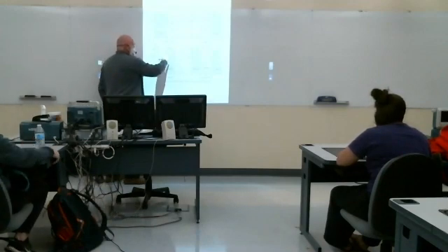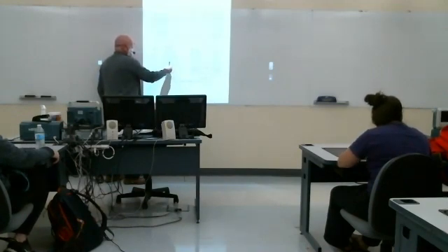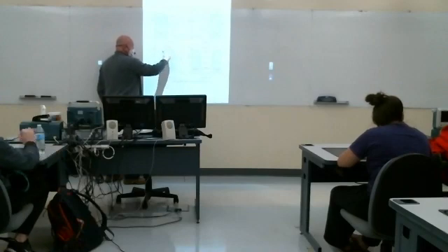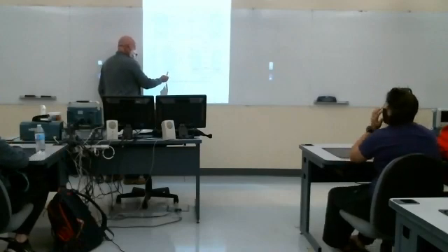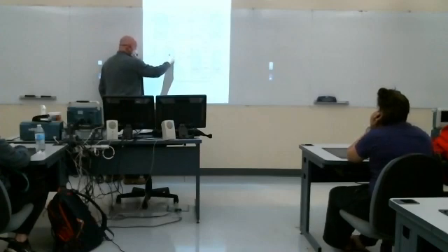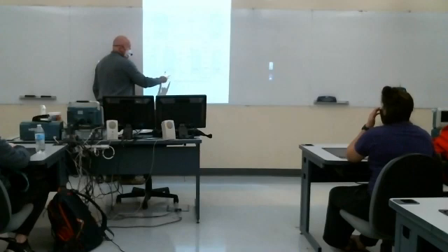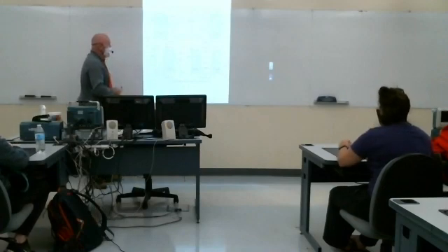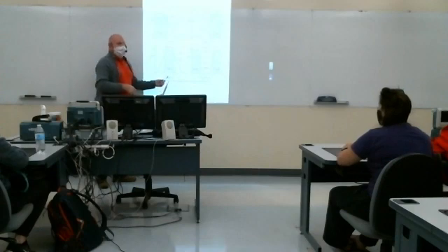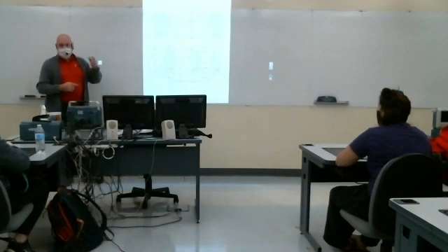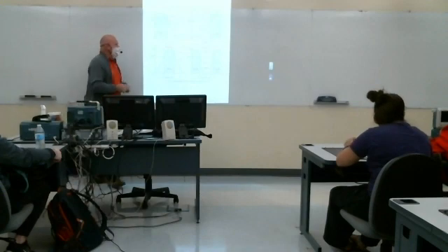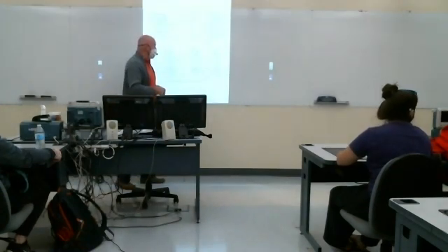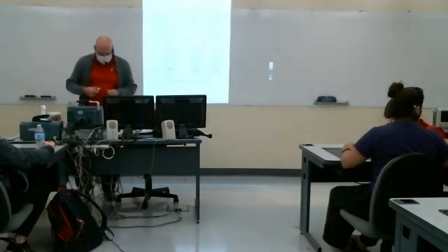And for a band pass filter, you've got 2 edges to work with. Again, we define the corner frequency to be the frequency above and below the peak response frequency where the response is down 1 over square root of 2. And so there are 2 frequencies on either side. These are typically built with RLC circuits. This omega 0 is also called the resonant frequency. And we use similar terminology here for the band reject filter.